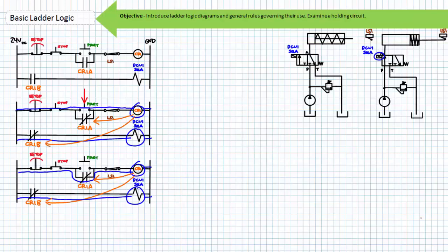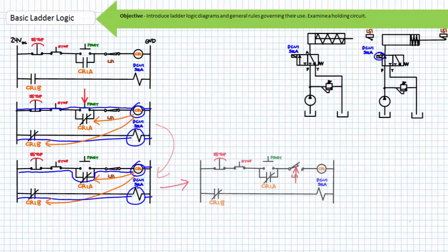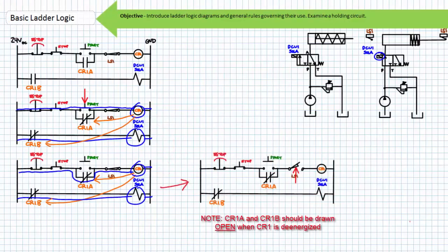This limit switch has in effect created a one-cycle reciprocation system. One-cycle reciprocation means that when an operator presses and releases the start button, the cylinder rod fully extends, strikes limit switch 1, and then automatically retracts, marking a complete cycle without the attention of the operator.